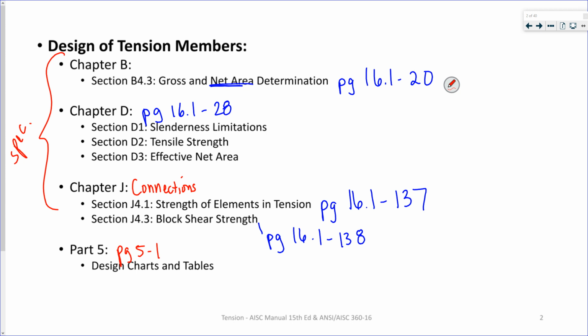Effective net area is assumed to be 0.75 times the gross. Oh, there it is. Use of table 6-2 for design members, page 5-3. So this is an assumption, right? This is where we start having assumptions in our tables. And so you have to always realize what assumptions these tables are making and if you're allowed to make those same assumptions.